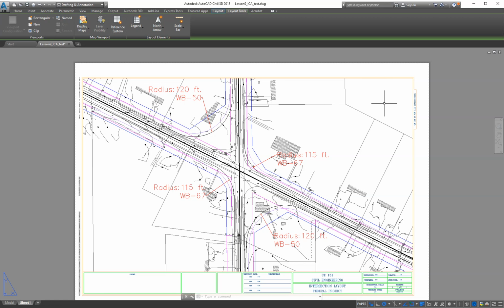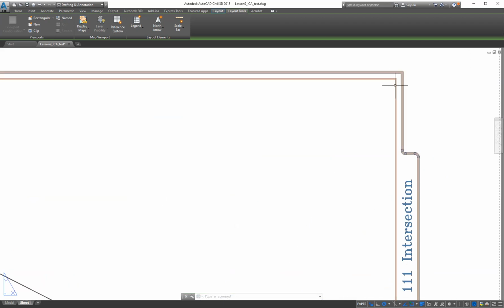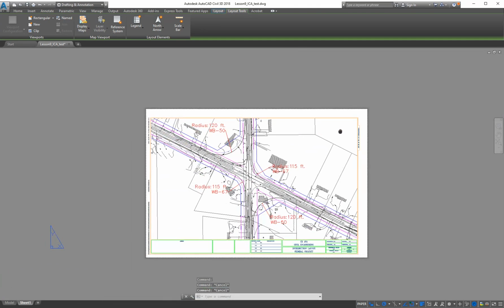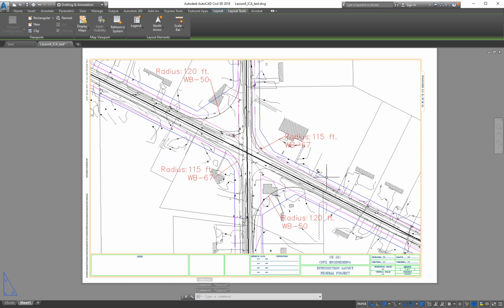And you can hide viewports other ways too, but we just tucked it in behind the actual border line of the title block, which is a block there. And so that's why you don't see it otherwise. It makes it a prettier drawing. That's why it's hidden down there. But we have to find that. We have to use this VP clip command.